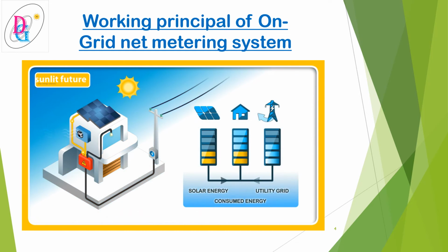You can always rely on the grid to supply extra electricity when needed, except during a power failure. When the utility grid fails, grid tie systems will not operate, not even on solar power. This allows utility employees to fix the power line safely without worrying about solar energy systems that are still feeding electricity into the power lines. In areas with frequent power cuts, an additional battery backup system is advisable to supply energy in case of grid failure.